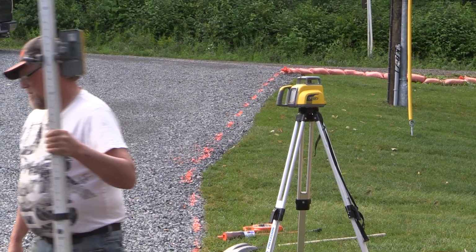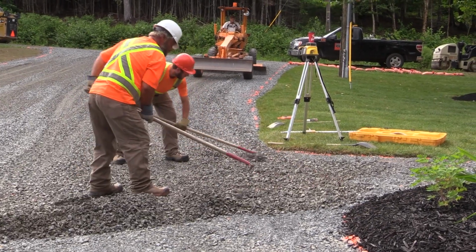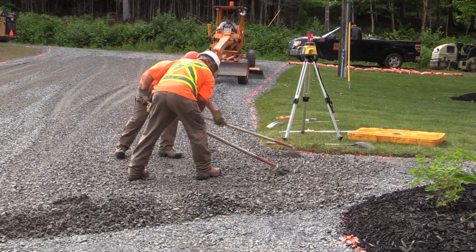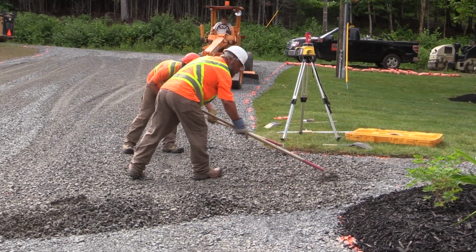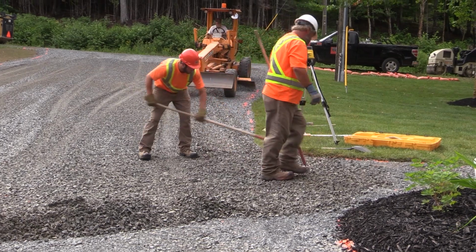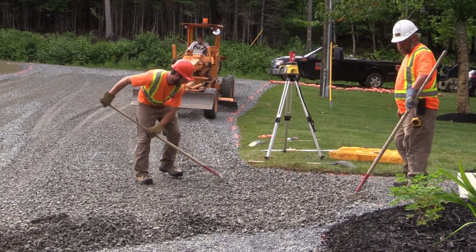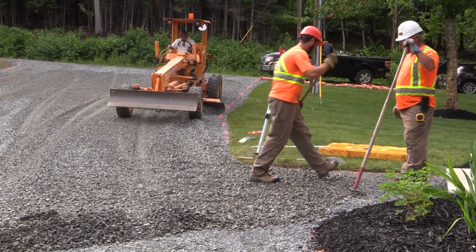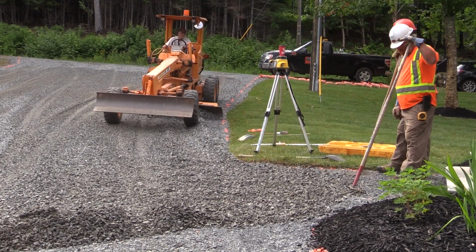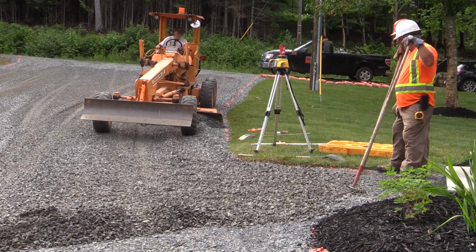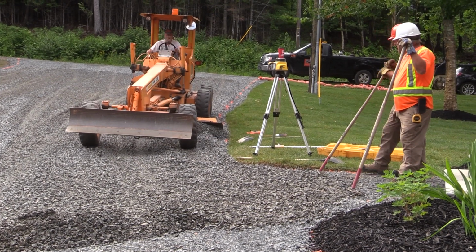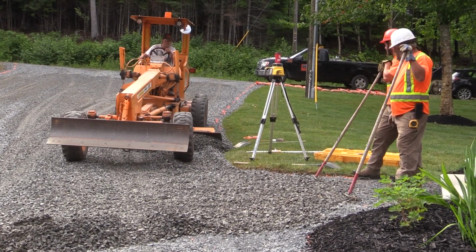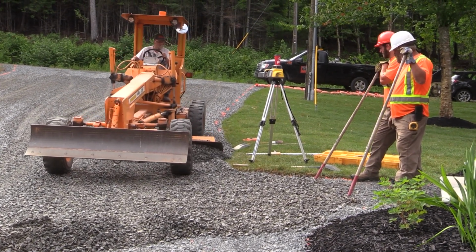Okay. The paving contractors need to make sure that the paved surface of the driveway is gradually sloped away from the house so that the water from the rain and melting snow flow towards the yard and not into the garage or basement. Using laser leveling and measurement tools guides them in the placement of the crushed rock to create the necessary drainage slope before the top layer of asphalt pavement is applied.